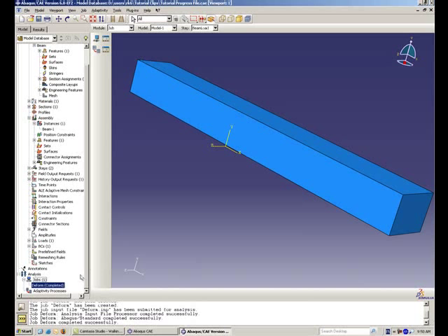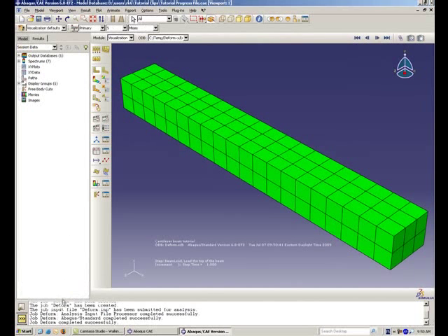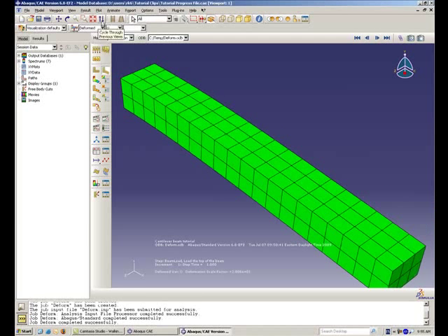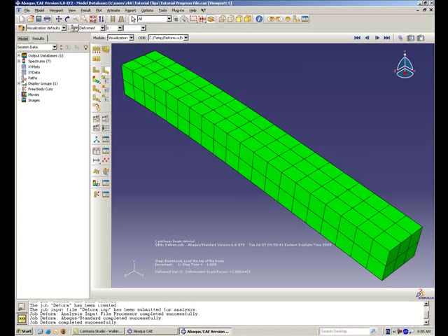When the status says Completed, right-click on Deform and select Results to enter the Visualization module. To see the deformed beam, simply go to Plot in the main menu bar and check Deformed Shape. Click the Auto Fit tool so the entire model is in the viewport.